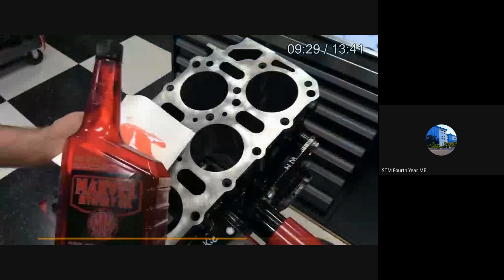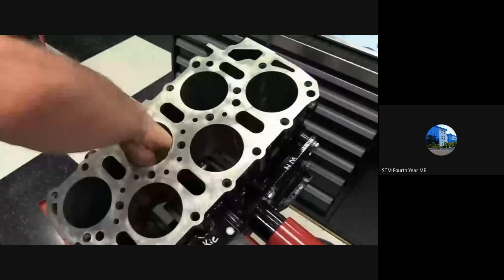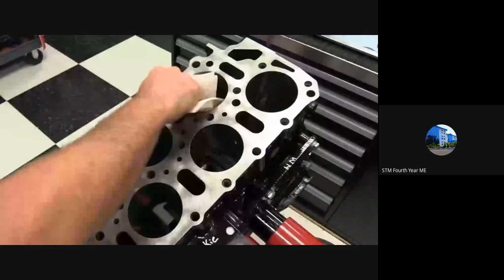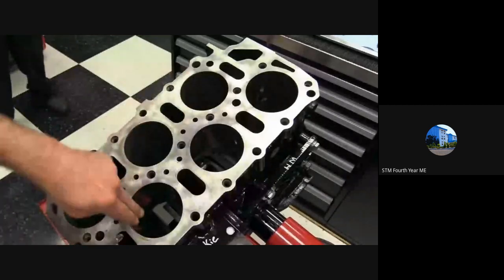In the same way, he's lubricating the inside of the cylinder bore before it is assembled into the engine. The crankshaft is already fitted. Now we have to fit the connecting rod and the piston inside the cylinder.